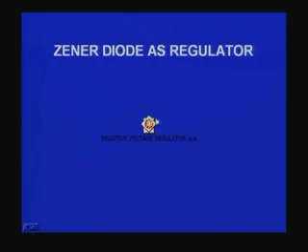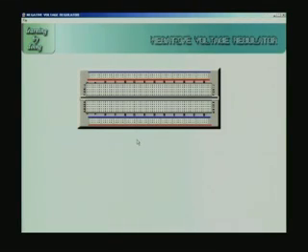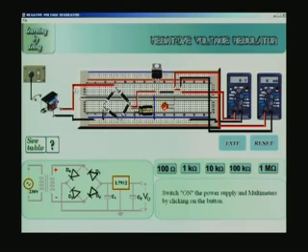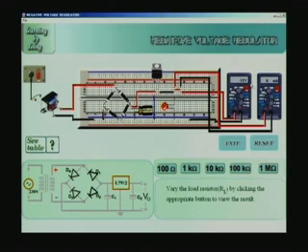Now let me quickly show you the circuit of a negative IC regulator. Again you can see there is a bridge rectifier, the transformer output is connected to the bridge rectifier, and a filter 1000 microfarad capacitor is connected here, and you have this regulator. It is similar to the positive regulator except that it is 7912, corresponding to negative voltage, and the voltmeters are all there. If I switch on the power supply and the multimeter, you would find the output is minus 12 volts. And if I now apply different loads, you can get correspondingly different load currents.